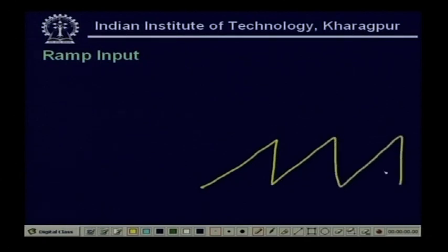A common example is the cathode ray oscilloscope: to measure voltage amplitudes we give the signal between the Y plates, and the sawtooth waveform is given to the X plate, so as to synchronize and make the wave stationary.